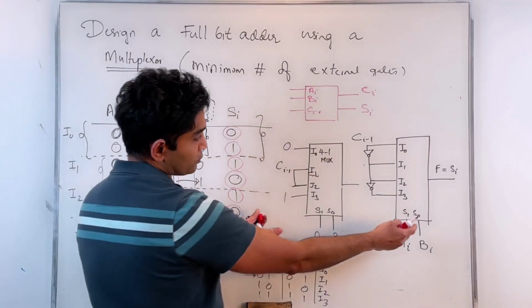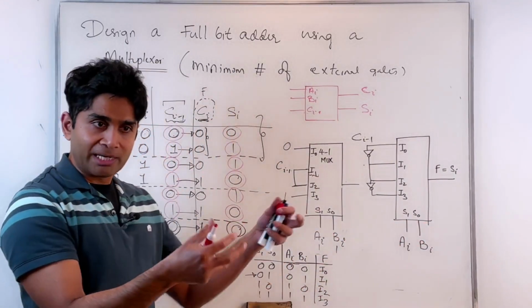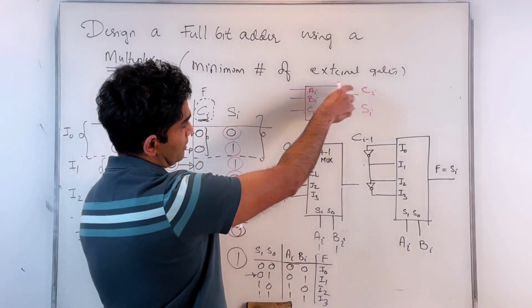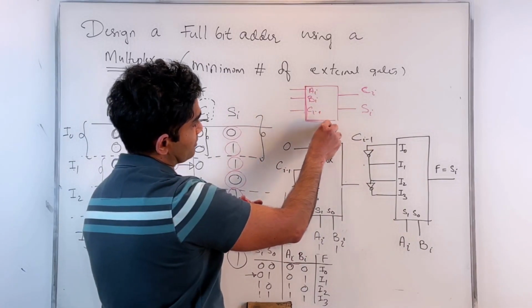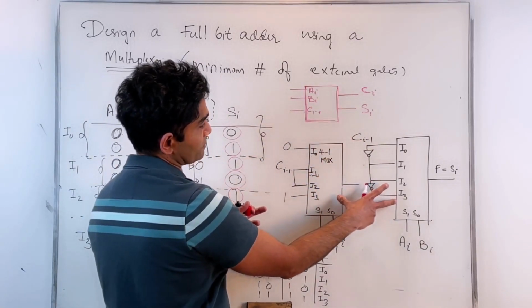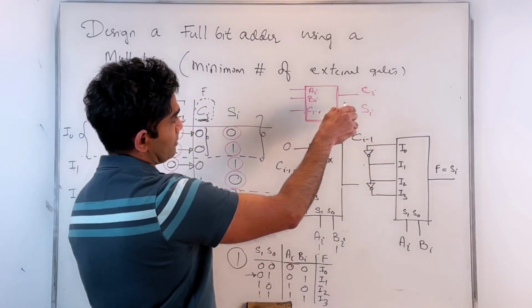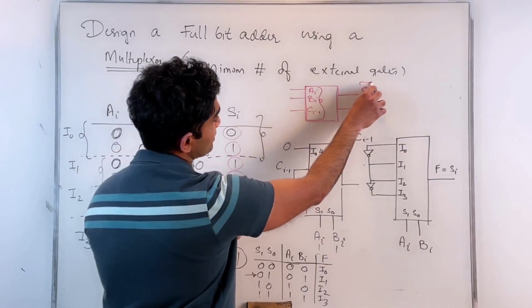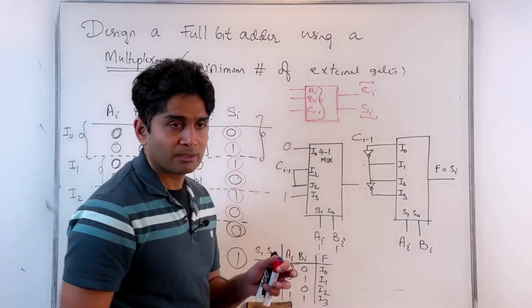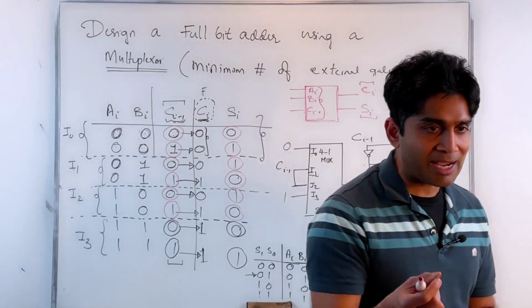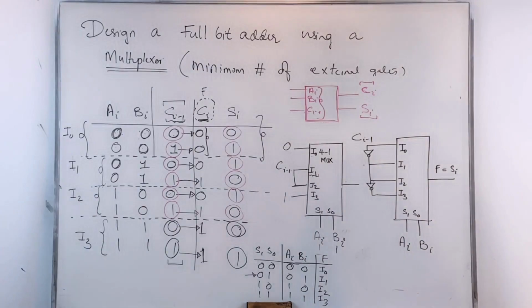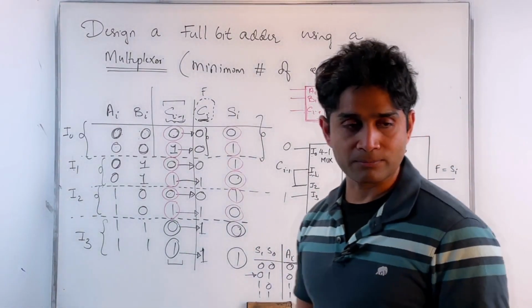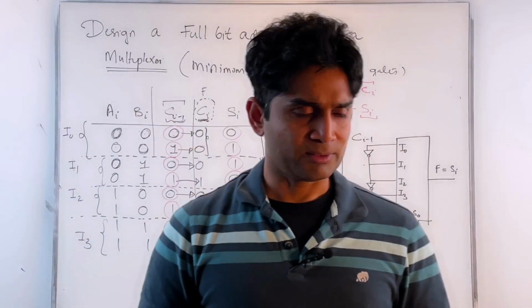And these two circuits, even though they look independent, form the same circuit here. So within this unit, I would have two multiplexers, functions of these common inputs, providing me two outputs, Ci and Si. Okay. That builds a single bit adder. And now, if I want to make it into an n-bit adder, of course, you can connect multiple ones as we have seen before, right? Does that answer your question?